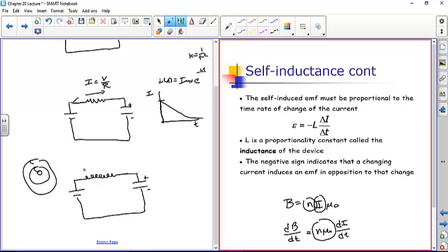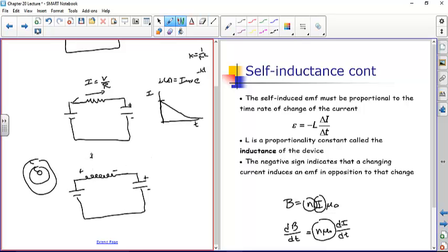So as the current's increasing, you have a voltage drop across the inductor. In the case where the magnetic field strength is increasing because the current is increasing, if this is greater than 0, then you have a voltage drop. If the current was decreasing so that the magnetic field was decreasing, then the voltage changes across the inductor. And it doesn't matter which direction the current's flowing; it depends on whether the current's increasing or decreasing, which relates to the changing magnetic field.